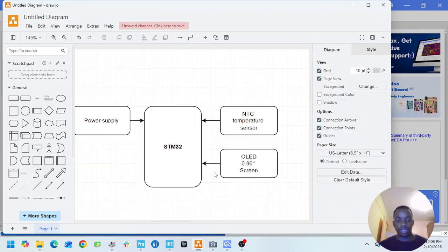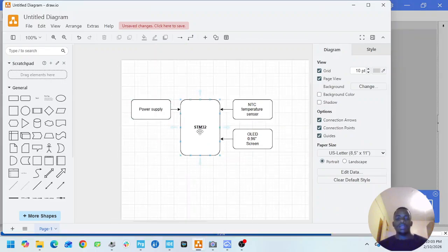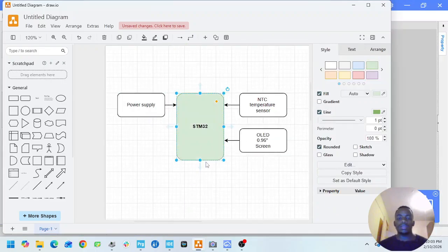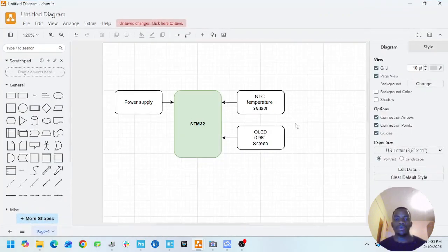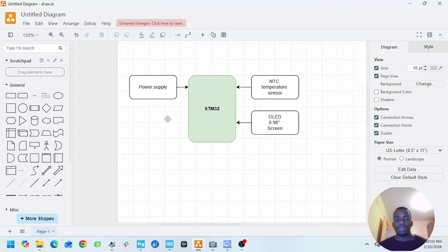Okay, so that's that. Then in industry, for the most part the devices that I've worked with expose user settings: the ability for the user to set things to do with device address, for example register addresses, and communication settings like baud rate, if you're using 8 bits, parity settings, etc.